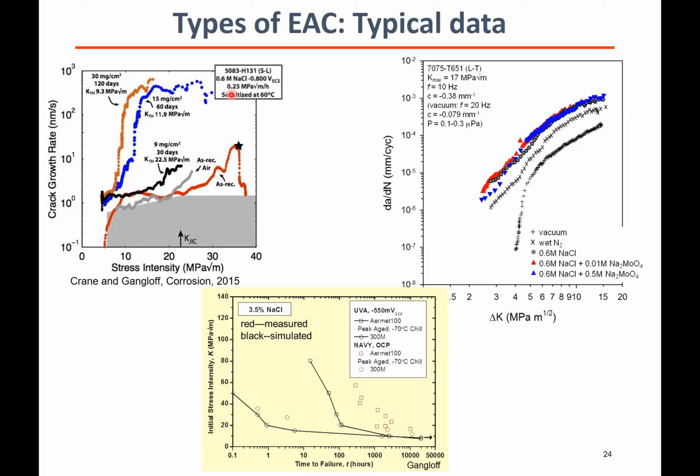And here it's some particular electrolyte, 0.6 molar sodium chloride, so it's not 1 molar, so there's some deviation from standard there. But the takeaway point is that this material is failing well before you thought it was going to fail, because of environmental assisted corrosion.